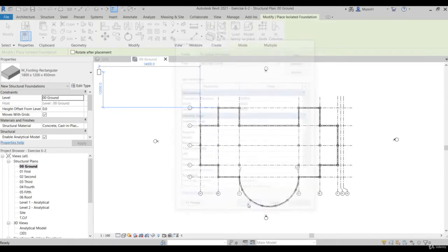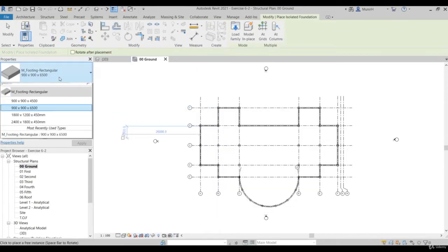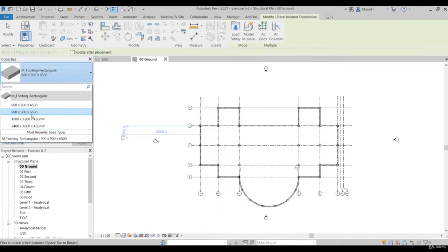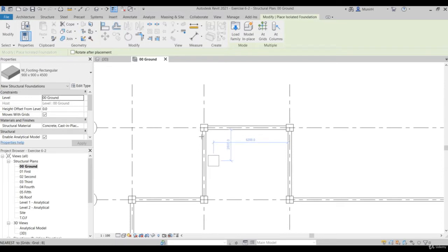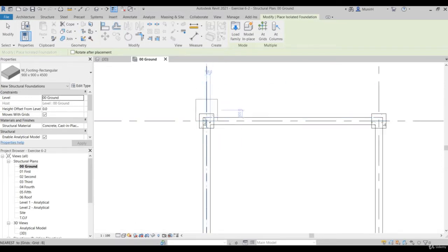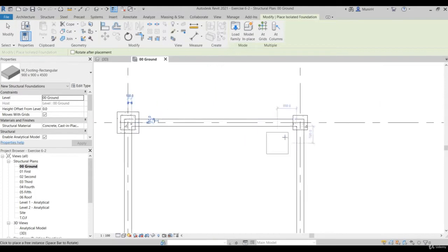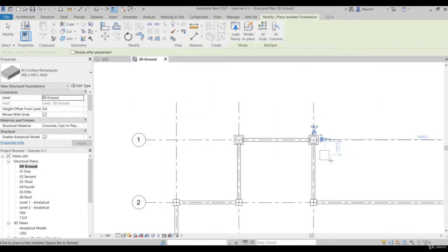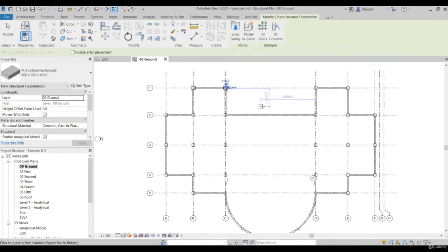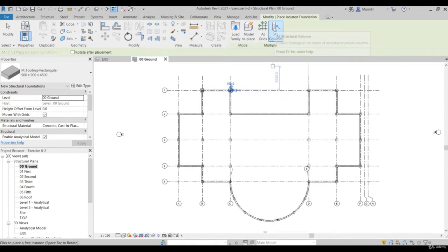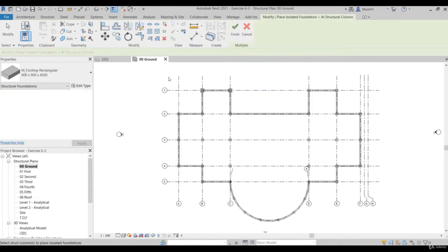We'll say okay. Now we have, as you can see, 4 sizes. We used to have 2, we added 2 more. I'll select the first one. Then you can add them one by one by going here. When the grid line highlights, you can click both of them. But what we can do is click on add columns. Add columns will help me do that faster.